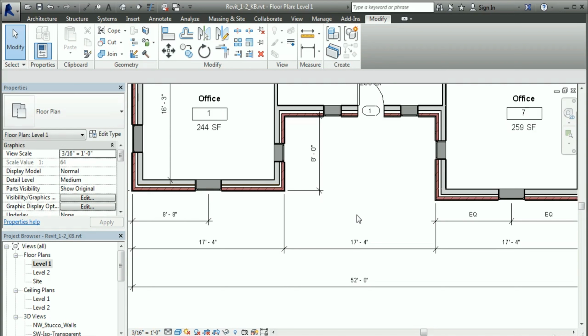If you remove equality constraints and you want to keep those elements from moving, you can also lock the dimensions by picking them and toggling the lock icons. Let's do another set of equality constraints between the front door and the two adjacent windows and the adjacent exterior wall faces. Now when you do this, these aren't bad.